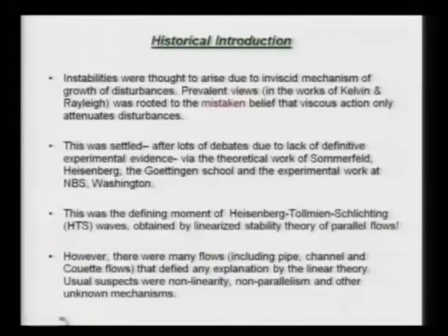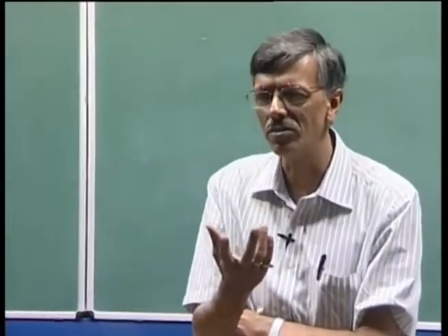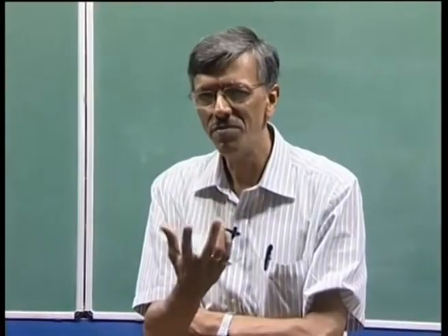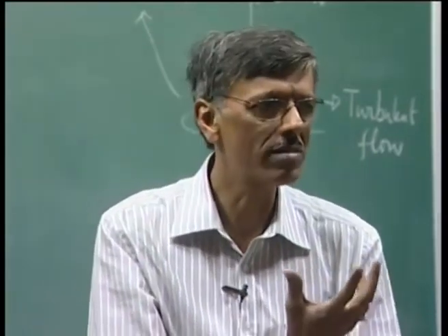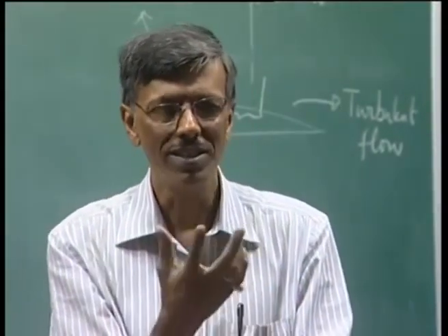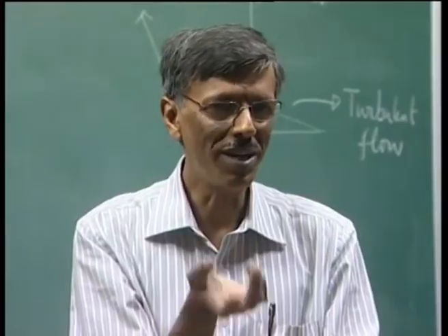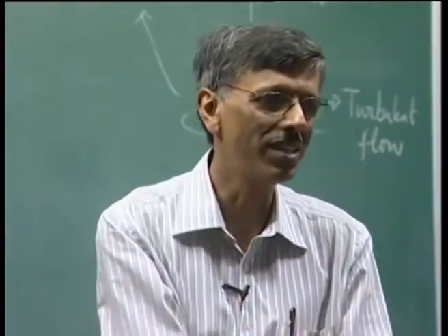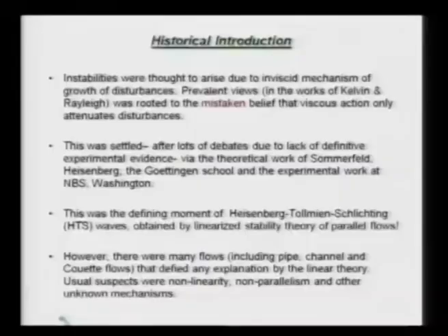Now, they also made this observation about why one should look at the inviscid mechanism. Their point of view was very simply this: if viscous action is there, it is dissipative, right. So, if there is some kind of a dissipative mechanism, that will actually damp out those disturbances. So, it is perfectly all right for us to study the inviscid mechanism, because if there are any viscous actions, they will only attenuate disturbances.